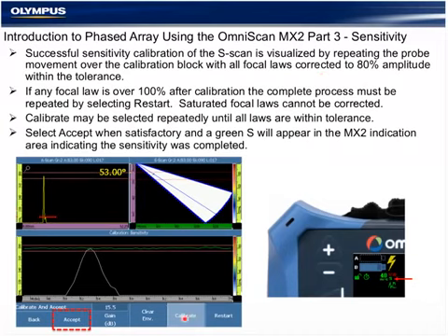The only reason that this window changes upon selection of calibration, where the line would not be within the tolerance, is because of couplant and pressure. It's directly related to amplitude, and you must maintain the same couplant and pressure.